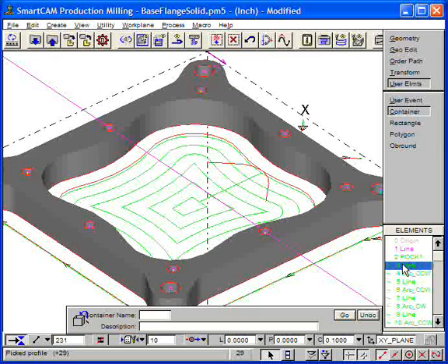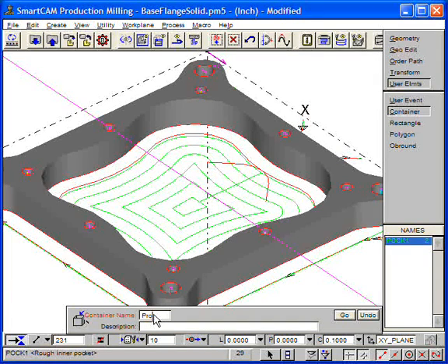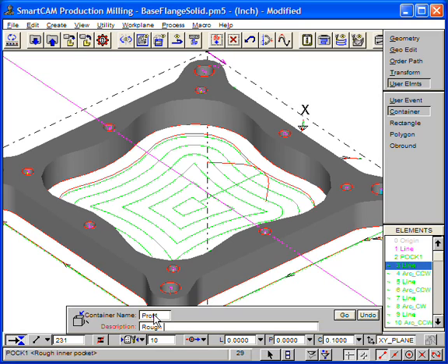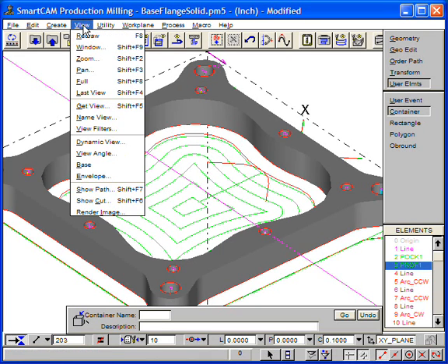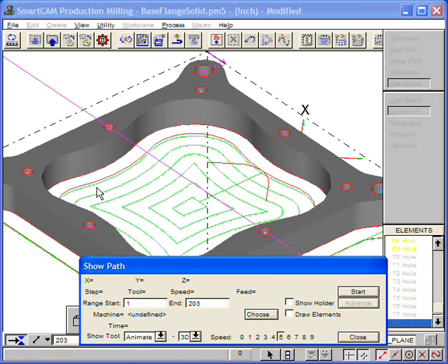We also want to create a container for the roughing profile. Because the rough pocket and profile toolpaths use the same step, we will create a new container for the rough profile toolpath so they will be easily distinguishable in the list view. Notice how the list view has further been collapsed with the new container. One of the benefits of collapsing toolpath into a single container is when you want to focus on the verification of a single process. Let's verify only the inner pocket with show path.